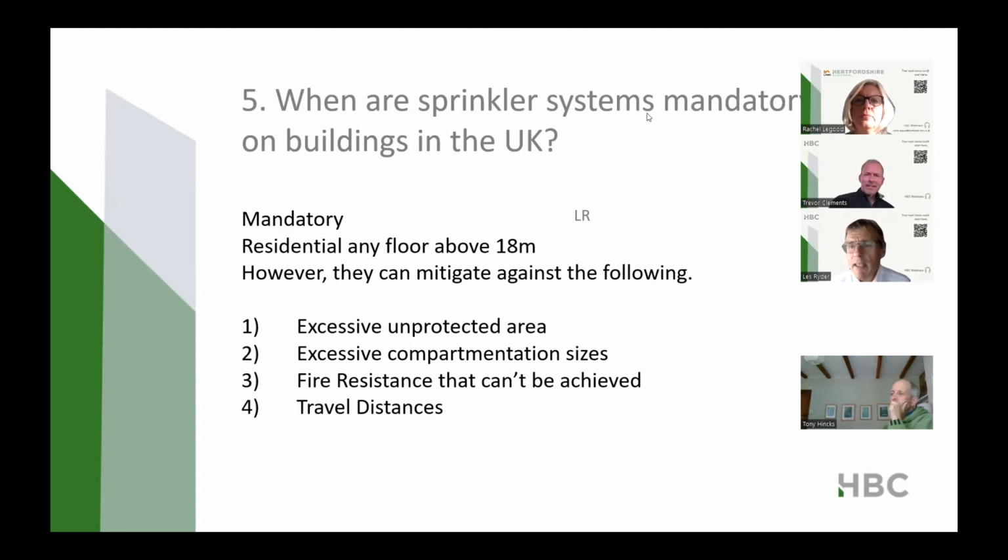It's common, an unwritten law, that it's very rare that a fire that's sprinkled exceeds 100 degrees in the compartment. The gas temperatures exceed 100 degrees in the compartment. It could burn all day and it wouldn't produce 12 kilowatts per square metre of energy at a building, as calculated in accordance with what Trevor was talking about. So it can mitigate against excessive unprotected areas, so we can bring buildings closer together where there's no fire resistance of the external walls.